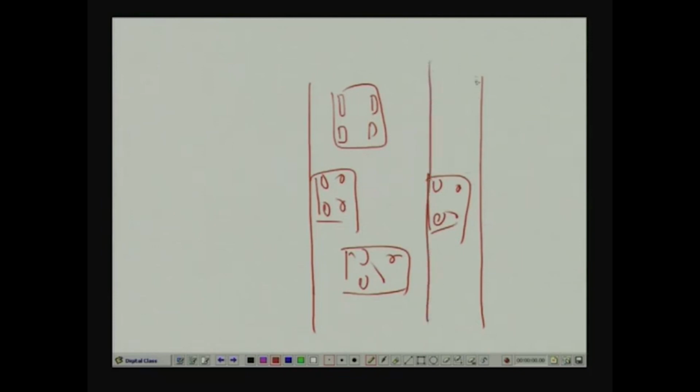They are not going to follow any particular path, they are going to be distributed across the carriageway bed. One vehicle may travel along this path, another vehicle along this path, another may take a slightly different path. So, the wheel load positions are going to be distributed across this width.